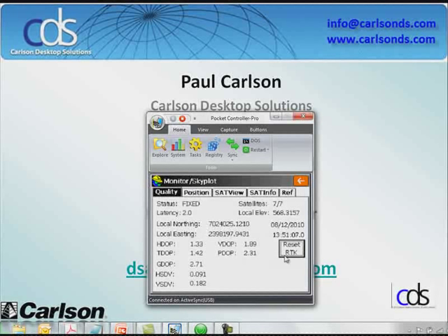The other important thing to bring up is the Reset RTK button. Years and years ago, the first time I picked up a GPS receiver, we went out on a site, started surveying, we got in a bad area we couldn't fix, so we floated, we waited a while, it never came out of float. So the first thing you did is you turned the receiver upside down. You dunked the receiver to let it clear out that position and start over, essentially. What really happened is the position didn't completely clear out. There was bad information, or could potentially be bad information left over in that position, multipath and other things.